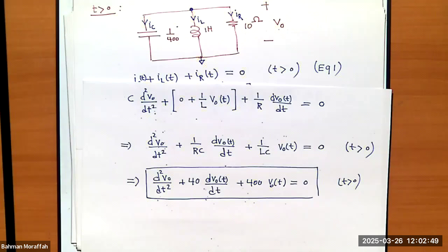Right off the bat, if I look at this equation, since there is no f of t over here, I know my K must be 0. Right? We're going to derive it by looking at the circuit at time infinity, but this is a sanity check. Since there is nothing over here, my f of t is 0. So my constant, K, must be 0. But for now, look at this circuit. Look at this differential equation. I know this differential equation is representing the circuit. So I've got to solve it.